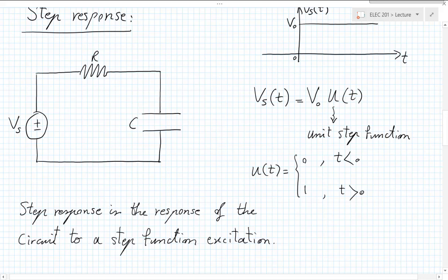So let's say if we thought about this current, and this as V sub R and this as V sub C. Now we've repeated this KCL that tells us the current in the resistor and the capacitor. Those two currents are the same, so I will skip that step now and just use I for both. What would VC, the step response in this case, be that describes V sub C?